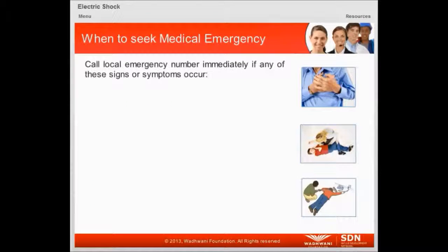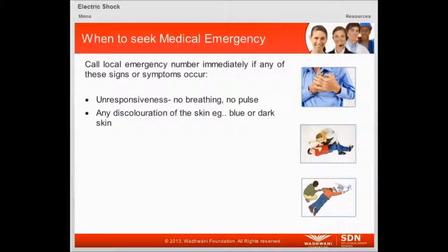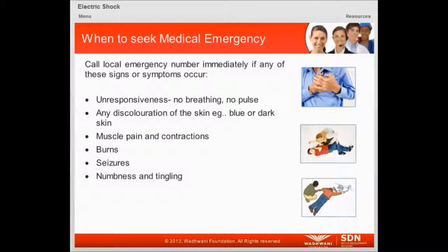If a person has got an electric shock, we need to call medical emergency immediately if any of these signs or symptoms occur: unresponsiveness, no breathing, no pulse, any discoloration of the skin, for example blue or dark skin, muscle pain and contractions, burns, seizures, numbness and tingling, unconsciousness.